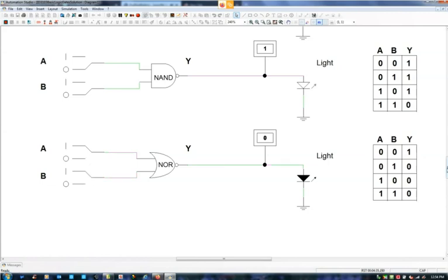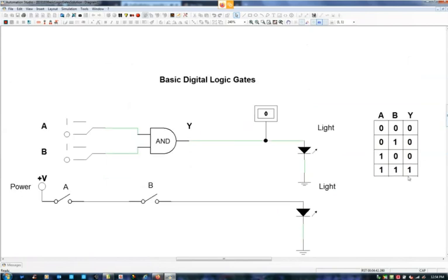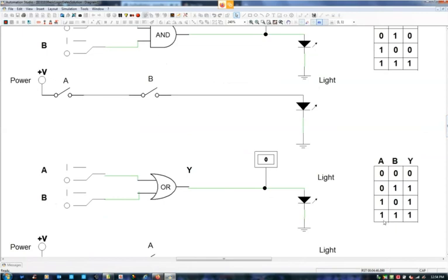And of course, the exclusive OR is, the only thing that's different is we have 2 highs up here make the output low. Let's go back down. There we go. 2 highs here make the output low. And there's one other, if it's in the module or not. An exclusive NOR. That might come up later, but it's just one of those things that the book sometimes talks about, sometimes doesn't. Now, each of these guys have what we call a Boolean expression.